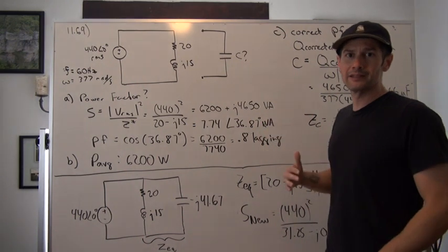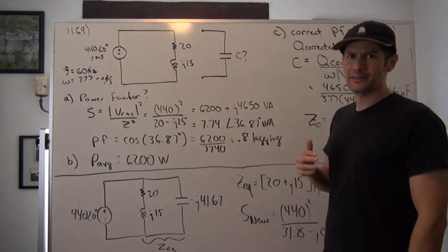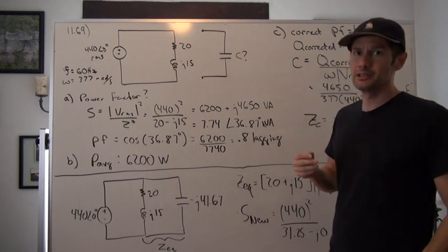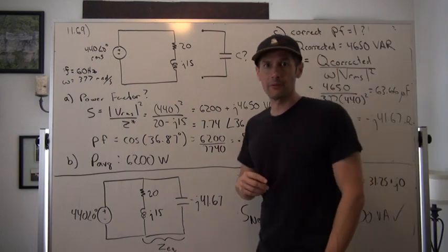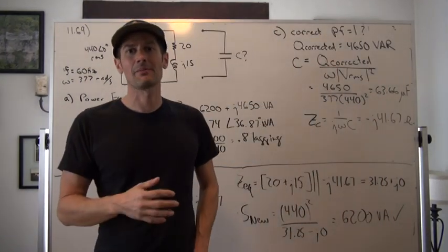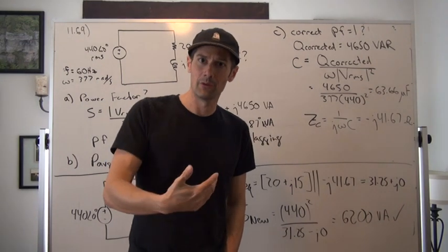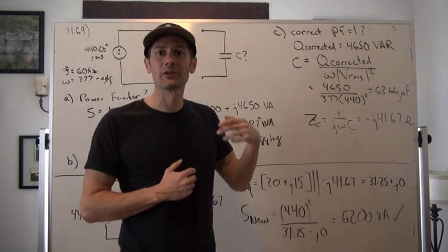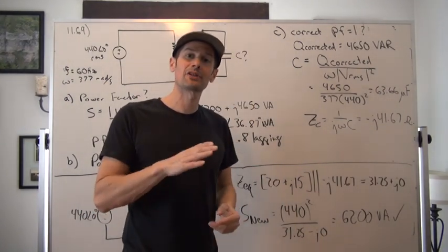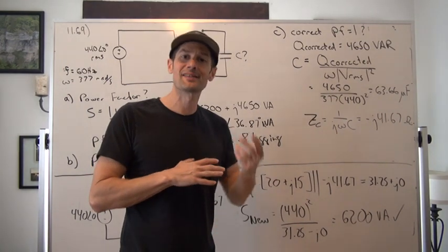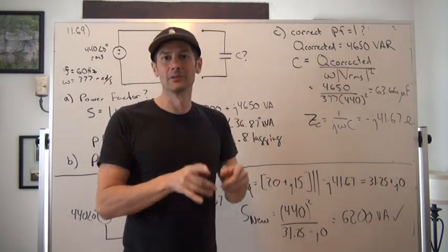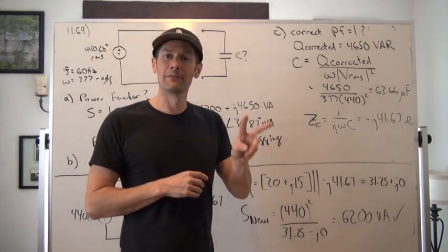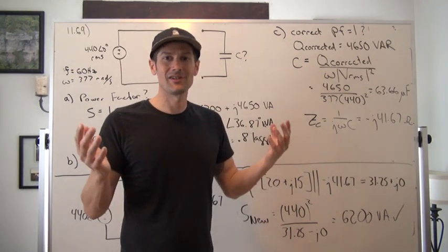We want to bring down that reactive power Q. We want to get that thing down to maybe close to 0. And essentially, if we lower Q down to 0, then what we're creating is basically a system that has a power factor of what we call unity, or a power factor of 1. And if we have a power factor of 1, that means that we've essentially caused theta V minus theta I to be equal to 0, or, in other words, the two phase angles of the voltage and the current are just equal to 0.